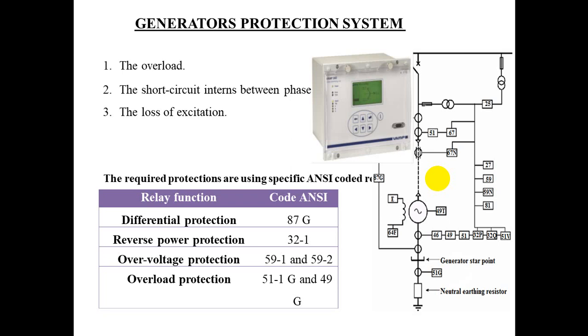This arrangement only detects overheating caused by overloading and doesn't provide any protection against overheating due to failure of the cooling system or short-circuited stator laminations. Although overcurrent relays, negative phase sequence relays, and a device for monitoring the coolant flow are also used to provide a certain degree of thermal overload protection.